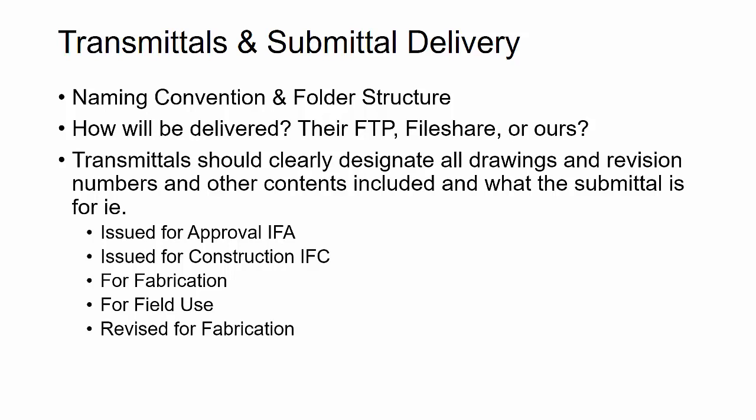And again, transmittals should clearly designate all of the drawings that are included in it, or if there's any CNC files or reports that are also included, that should be clearly designated and marked on the transmittal, and then what the purpose of that specific transmittal or submittal is for. Now, again, if the job is a little bit bigger and you're submitting by sequence or phase, then you should also make sure that you include that there. So that way the fabricator knows that, hey, this is exactly the right order and the package that I was expecting, and they can see which date that was submitted to them.